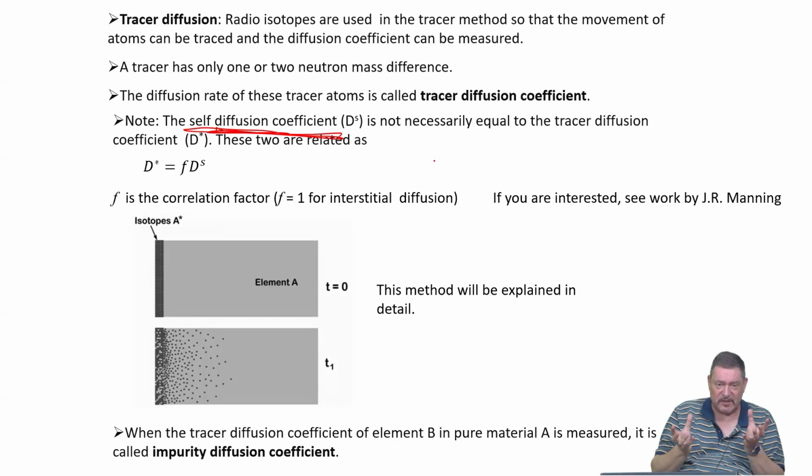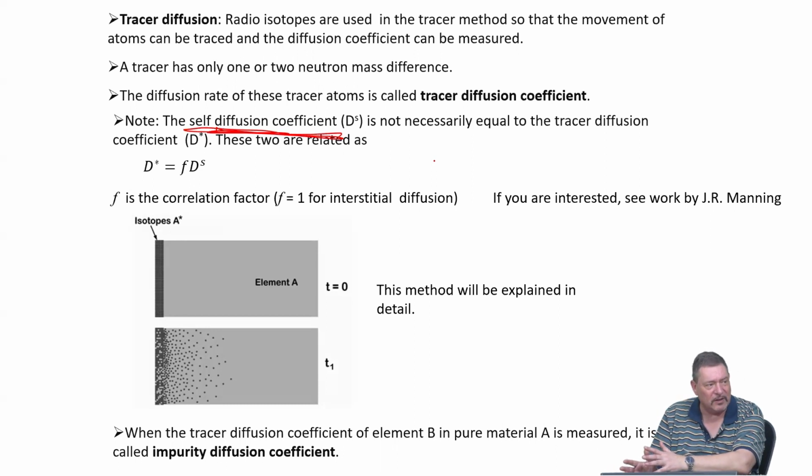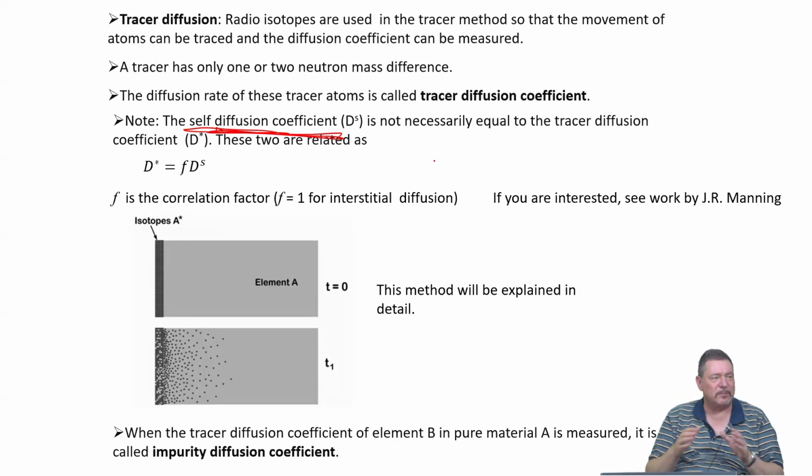And these 5 principal frequencies are used to calculate principal correlation factors under different conditions. In reality, we measure and see what the correlation factor is, because otherwise you do a computational study. You cannot do it by hand analytically. But just to let you know, tracer diffusion coefficient and self-diffusion coefficients can be transferred rather easily into each other, but they are not the same if substitutional diffusion is taking place.